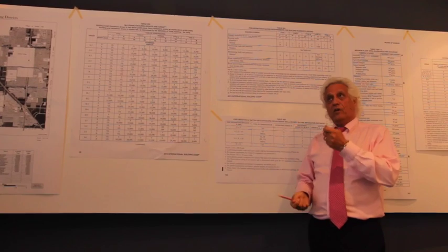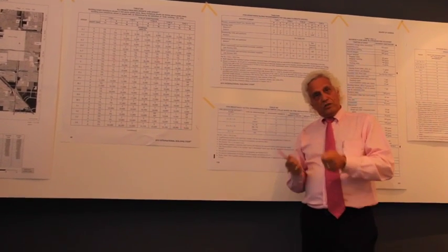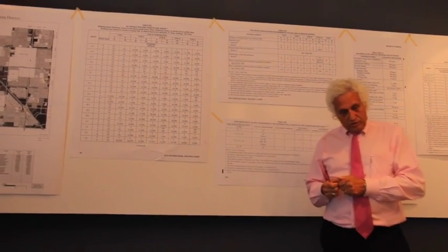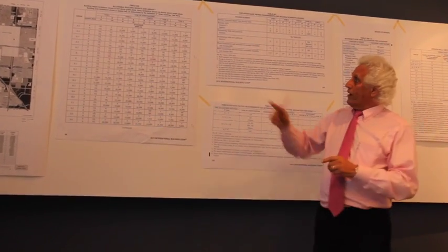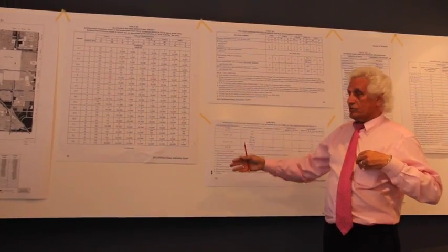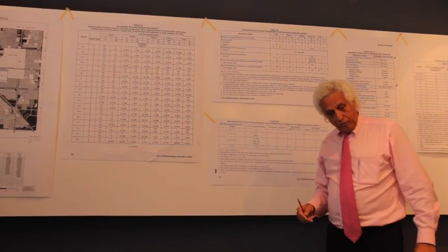And that's the analysis that we do when we start to look at structures. First you have to establish the use group, and then you have to establish the actual construction type, because then that allows you to move further into the code.